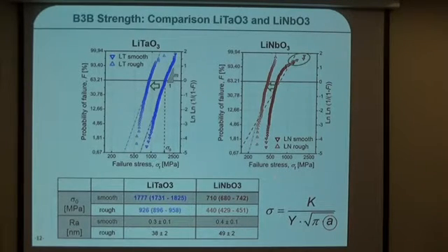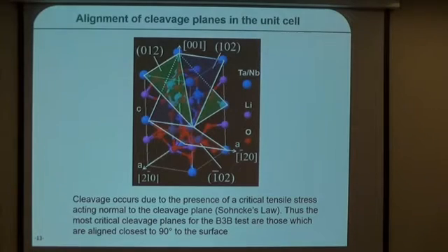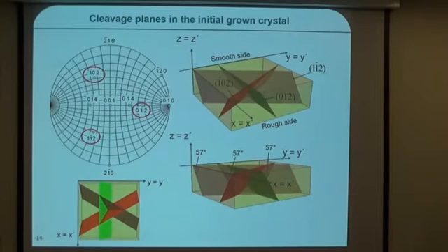But what we actually don't know is the reason for the big difference between the two materials. What we do know, especially in brittle single crystals, is that fracture toughness is strongly dependent on the direction of our crystals. So we know that there are cleavage planes inside our samples, and what we wanted to find out was how these cleavage planes are aligned in the rotated samples.